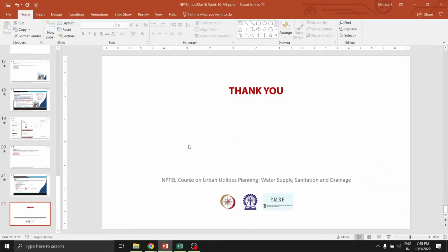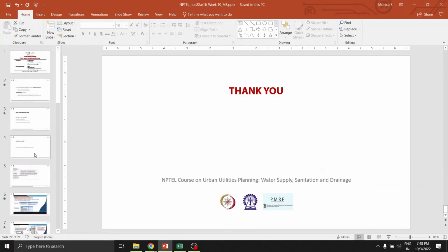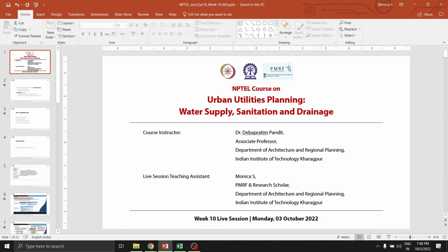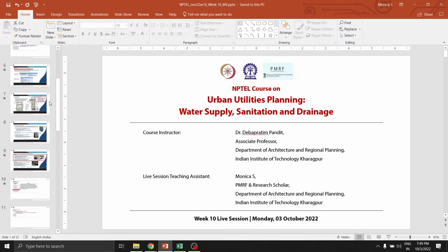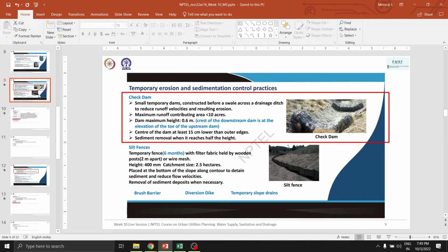It was quite basic because most of the answers are repeating in the current assignment. During the final examination, will all the constants be given, or do we have to assume? Most of the constants will be given, but some things, for example, Manning's roughness coefficient, or the CH value. For example, cast iron pipe is always 130, right? They might give you the material, and you will have to remember the values from the lectures. Only the coefficients, nothing else.